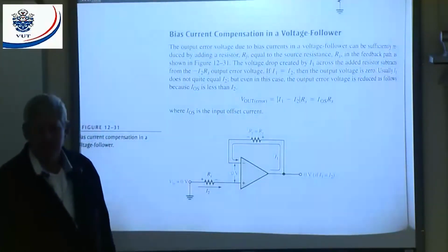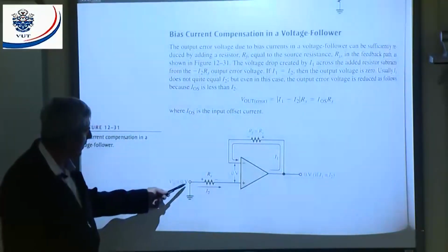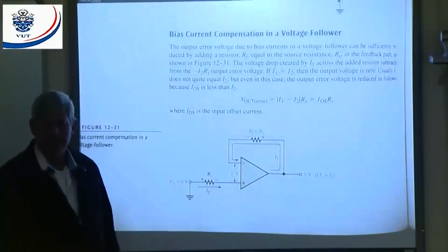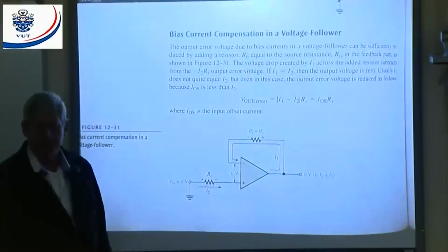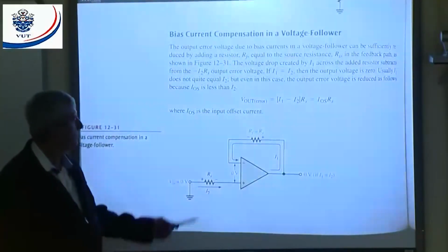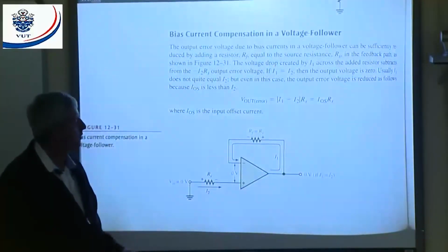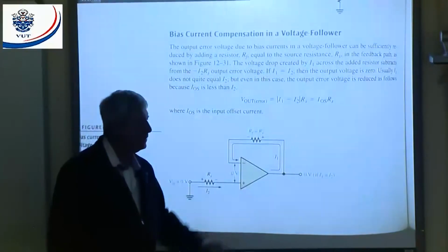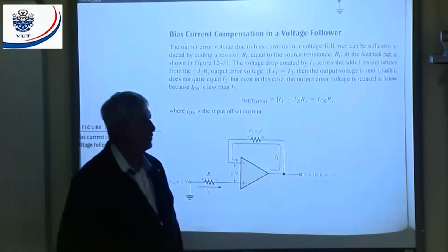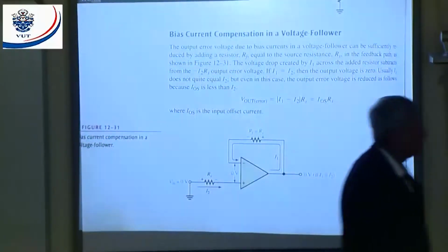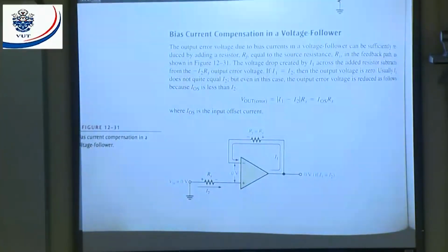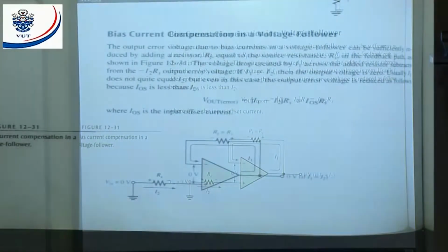Right, here's the open loop frequency response of an op amp. That will basically be the open loop response of a 741. If I look at 106 decibels, that's the gain. You see here on this axis I've got my open loop gain. 106 dBs, per unit, is going to be equal to 200,000, all right?